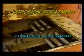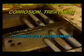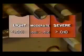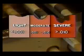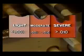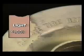Corrosion damage assessment is required to determine whether the necessary repair and rework is within the limits set by the manufacturer. The first step in assessing corrosion damage is to classify the corrosion as light, moderate, or severe. Let's look at corrosion assessment of aluminum. Light corrosion is distinguished by discoloration or pitting to a maximum depth of 1/1000th of an inch. This is about 1/4 the thickness of an ordinary sheet of copier paper. Light corrosion can normally be removed by hand sanding.